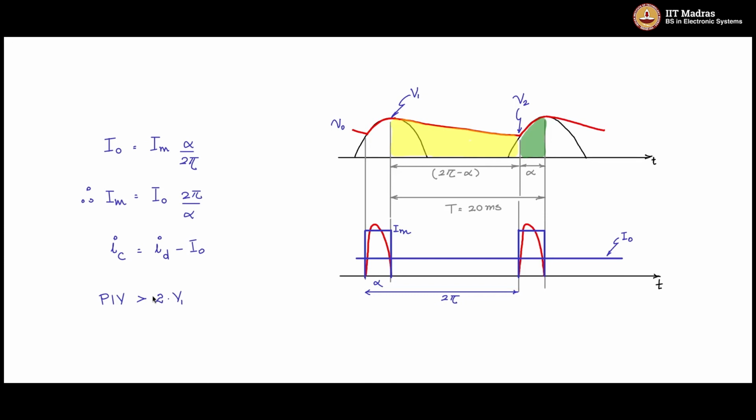So whatever may be the rating of the device that you have chosen, do not apply a stress more than 75% of the rating. So if you are having a 100 volt device, do not apply more than 75 volts as the voltage stress for the device. It could be diode, it could be BJT, IGBT, MOSFET, as a general thumb rule for any device selection.